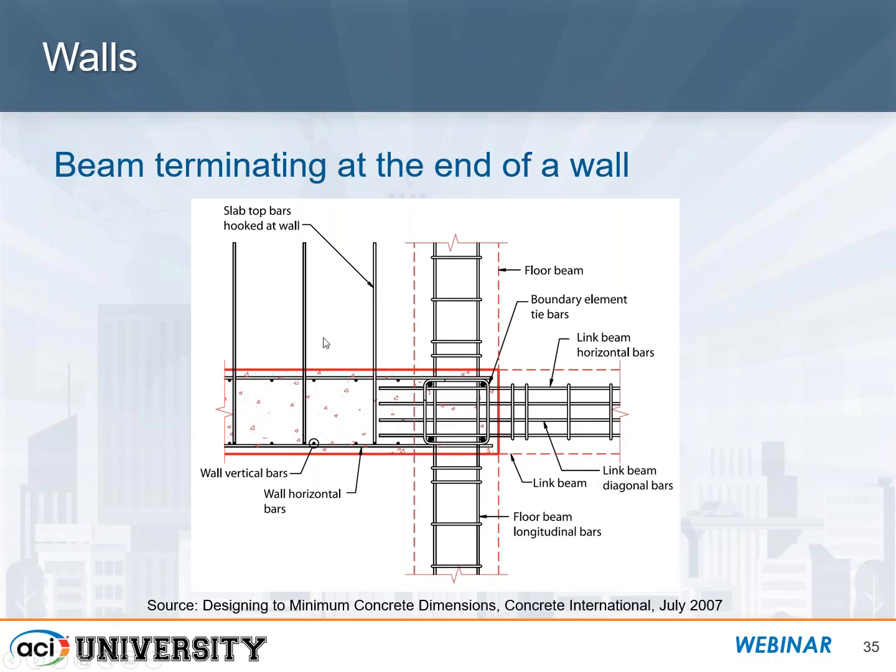So taking all of this into consideration with the thickness really is important to do, because this end of the wall can be loaded up with steel very quickly, and maybe you only need, say, a 12-inch wall for strength, but providing a 14 or 16-inch wall may be helpful to alleviate any possible congestion that could occur at the end of the wall. So just something to think about based on what framing you have in this particular case.